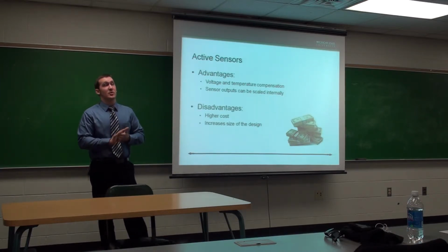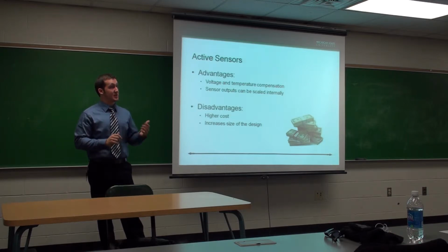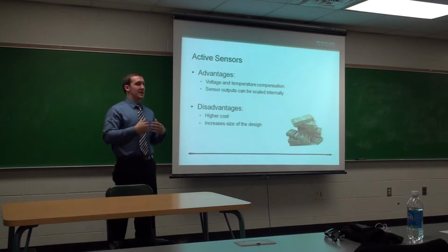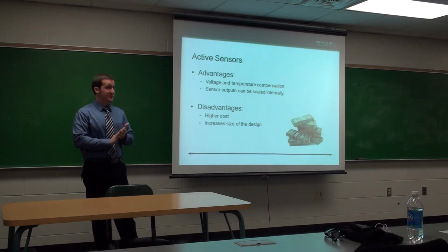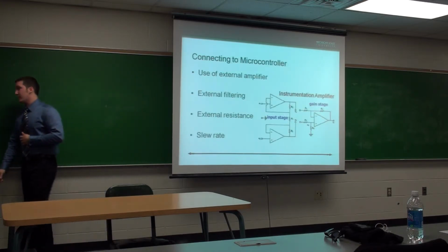Additionally, as I mentioned before, active sensors are capable of scaling their own outputs internally, meaning you can eliminate amplifiers and other circuitry to connect up to your sensor, making it much simpler in your design. However, active sensors tend to be more expensive than passive sensors, and they will also increase the total cost and size of your design because you need these additional active circuitry elements in order for this sensor to operate.